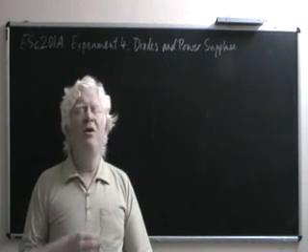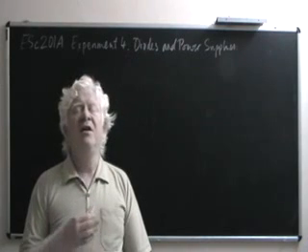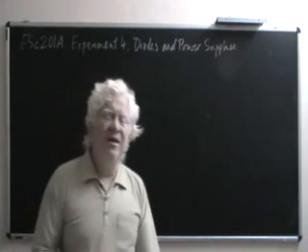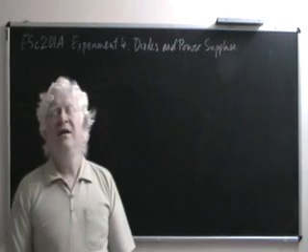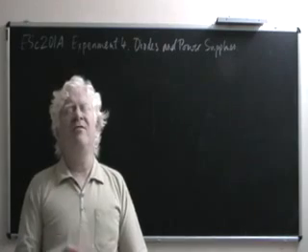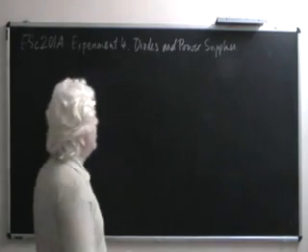And when you apply a voltage in the reverse direction, the resistance is nearly infinity. For an ideal diode, of course, we say that the forward resistance is indeed zero and the reverse resistance is nearly infinity. So let us plot the characteristic of the diode with respect to voltage and current. It would look like this.